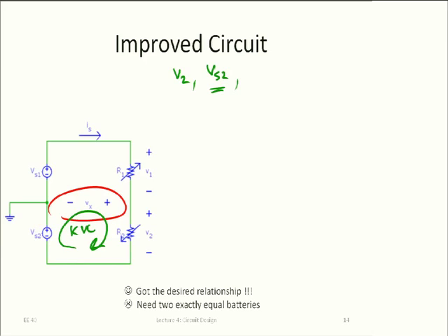Is would be equal to (Vs1 plus Vs2) over (R1 plus R2). Be very careful when you copy these equations. Remember my bet with the $20? Hey, I lost them, okay? So sometimes there is an error in here, so be careful. Don't just copy the equations, rederive them. Okay, and then once we have Is, we can figure out V2 is equal to Is times R2, okay? And once we have all of this, we can solve for Vx.